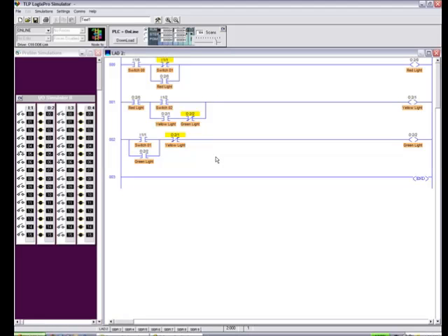Okay, so moving on to page 9 of the tutorial itself, we can also add documentation rung comments to the code itself. If we return to the instruction palette, we now want to highlight rung 0 with our left mouse button, and then we're going to right click, or you can simply right click straight away if you hover over rung 0 there. We're going to select edit rung comment.